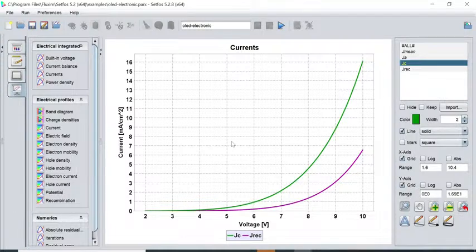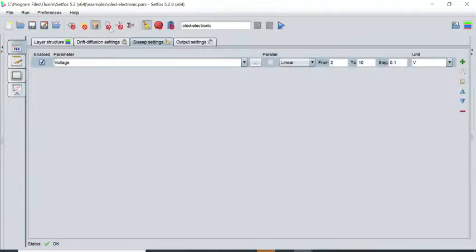Now to perform the electronic to optical simulation, we have to solve the drift diffusion equation and to calculate the exciton distribution as an emission source for the optical light out coupling. For optical coupling, the emission module must be activated additionally. So I click on this bulb sign to activate this module again.